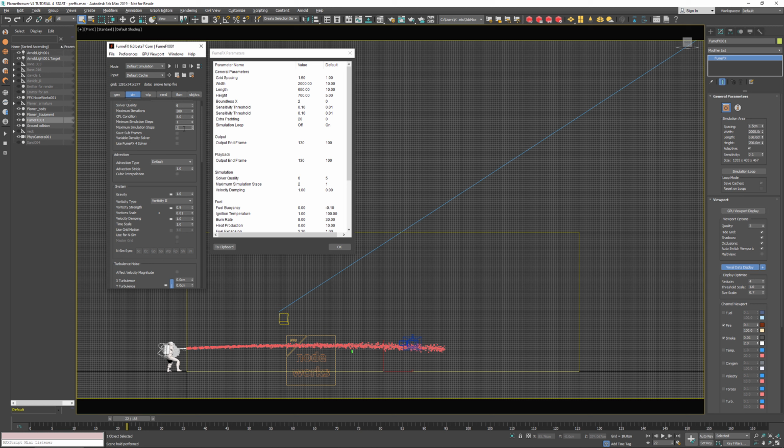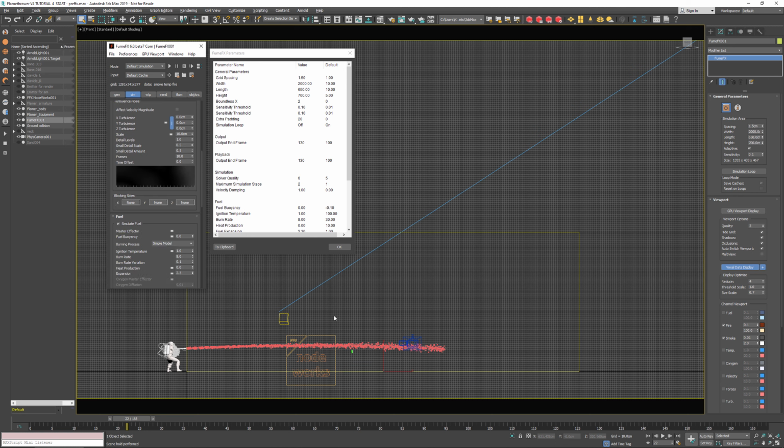But with simulation steps, usually bigger doesn't mean better, because with more sub simulation steps you probably get more diffused smoke, as during each step all the fields need to be interpolated and moved along the grid by the velocities. And now the simulation uses velocity damping, which I usually avoid, but this time it was necessary to reduce the horizontal motion and to increase the vertical motion by using the temperature buoyancy, and also use smoke buoyancy to increase the vertical motion compared to the horizontal motion.